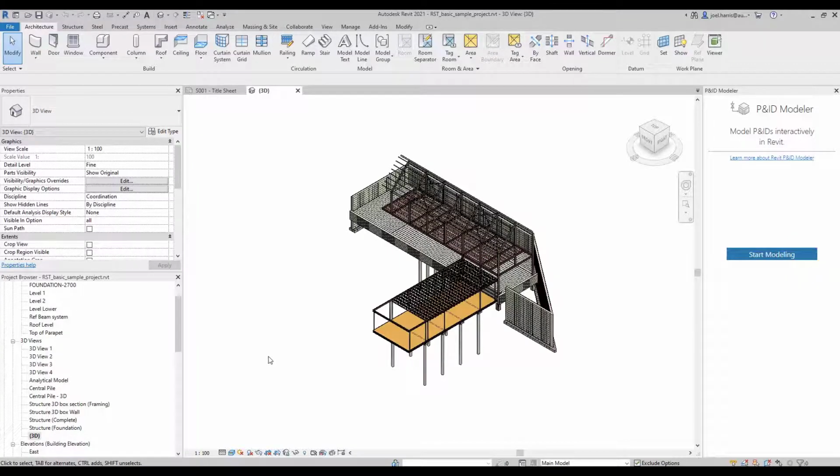Exporting a DWG file from Revit so that it can be used in AutoCAD Plant 3D is a fairly simple operation. The main thing is to make sure that you've reduced the level of detail in your Revit view and that you're in a 3D view, as shown here, of the model so that the geometry you expect to be exported will be exported in 3D. So in this case, if I had any small holes or layers that I could turn off, geometry that wasn't necessary for AutoCAD Plant 3D, it will save you a lot of time in orthographic generation as well as in overall model performance.